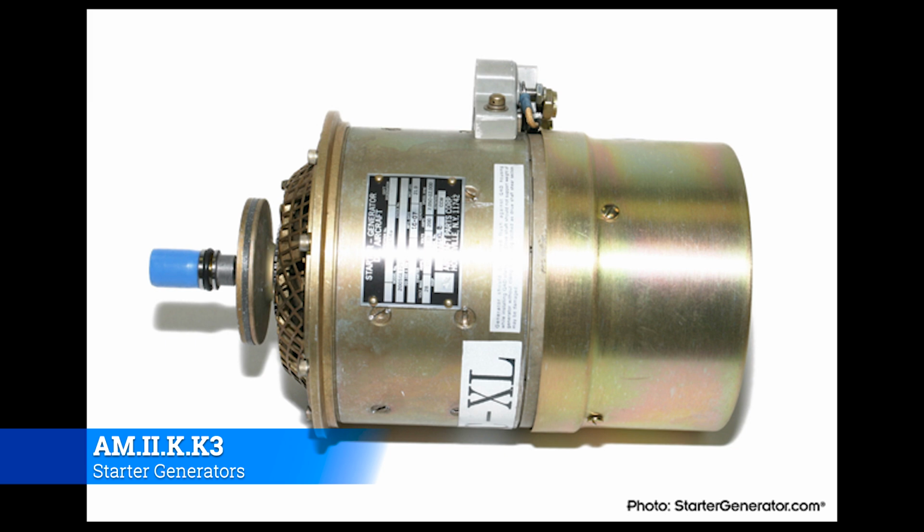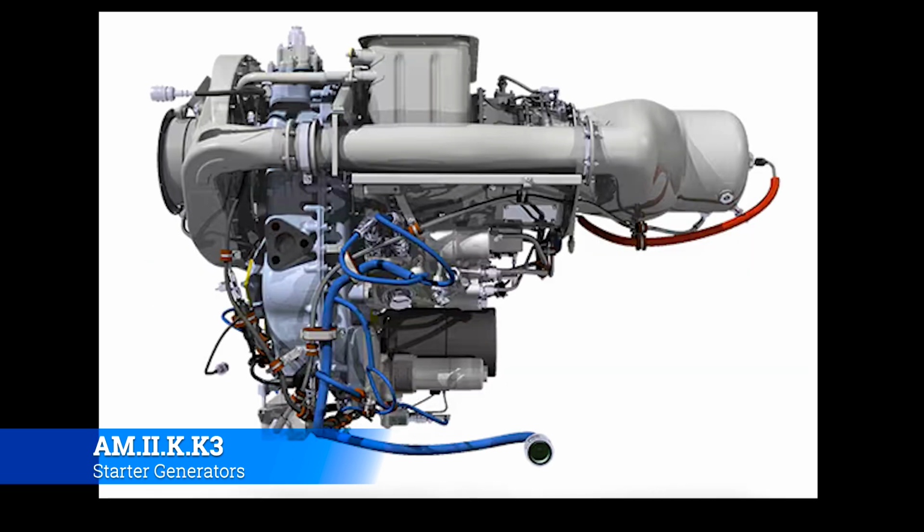There are several terminals that will go onto this aircraft, and the reason is that not only is there circuitry for going direct to the battery to spin the motor to spin the engine up to get started, but there's also another pathway to go to the battery charger and then into the battery and indeed to the rest of the aircraft system.